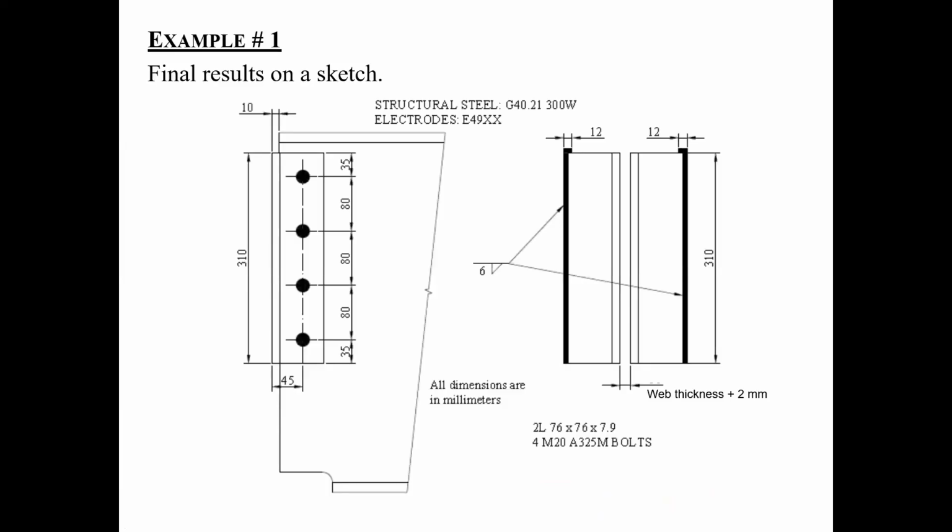So now, when you're showing your stuff on a sketch, I want you to notice a couple of things, okay? Your column would be right here, guys. The flange of your column would be right here, and then the welding would be right along this side. In other words, this weld would be there. So here what you're showing is that this is a side of the beam that's going to get bolted, okay?